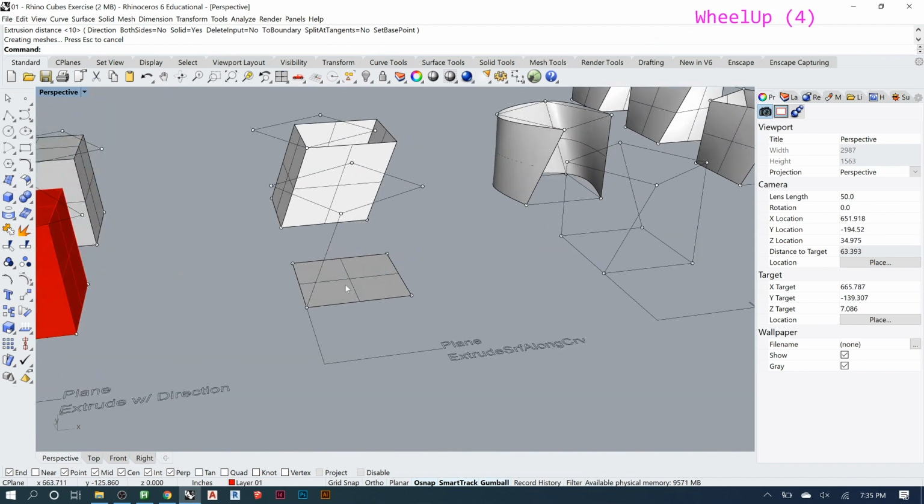And then here you can also extrude surface along a curve. So what this one lets you do is kind of like the sweep, but instead of just the line, you can extrude a whole surface. So in this sense, we're just doing it along a line, but that line could be curved or have some sort of other shape to it. So all of these are basic, I would say they're not at the primitive level, where you just click box and it gives you a box, but they're one step up. It's the next step to making a more complex form.